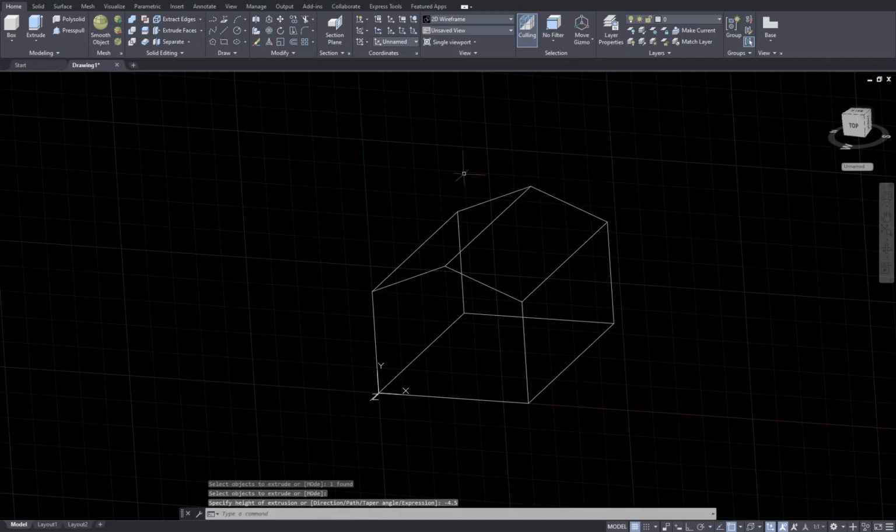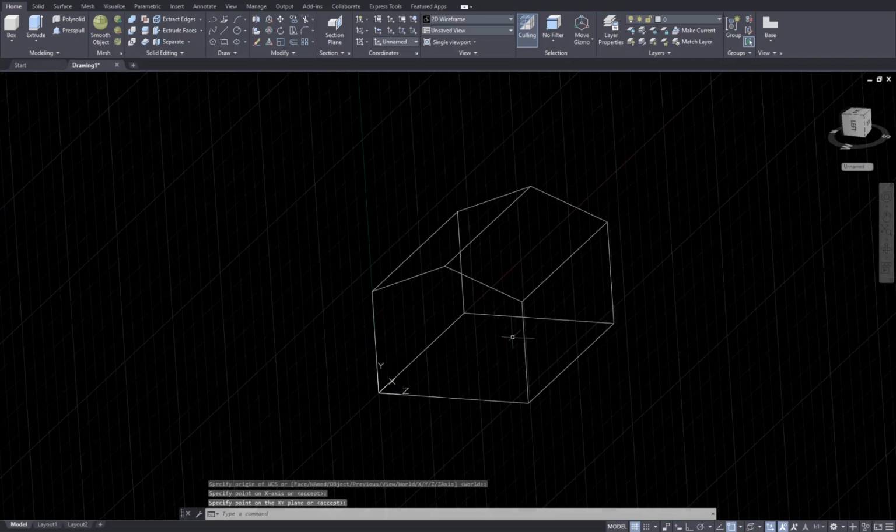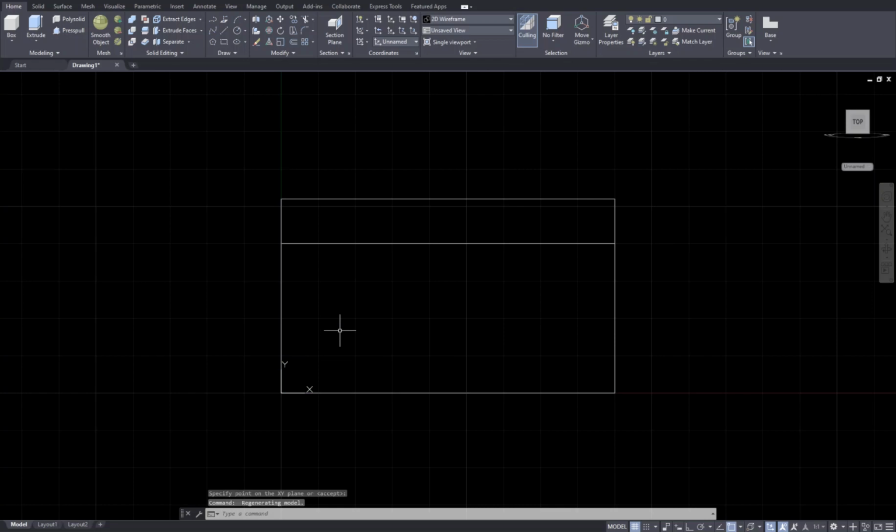We have dormers on this building, so to deal with that, we're going to have to go to the front surface of it. I'm going to carry my UCS, user coordinate system, with me. I'm typing UCS, enter, selecting this corner, and then X, then Y. Now I'm here, and if I change my viewport and go with the polyline, start from 0, 0, enter.